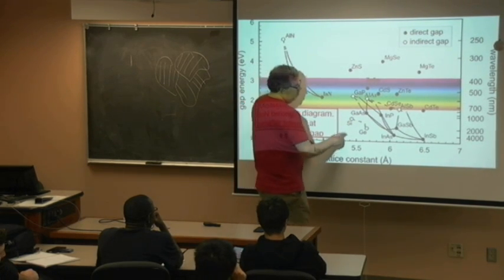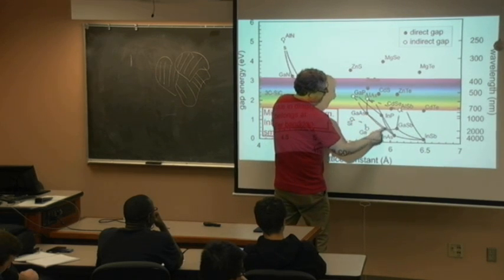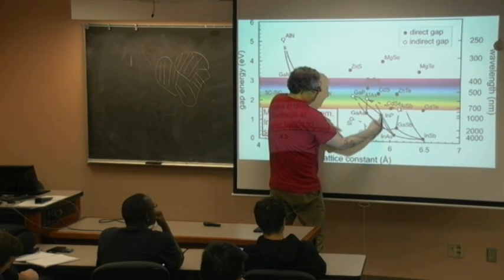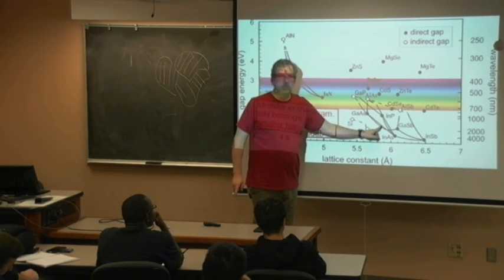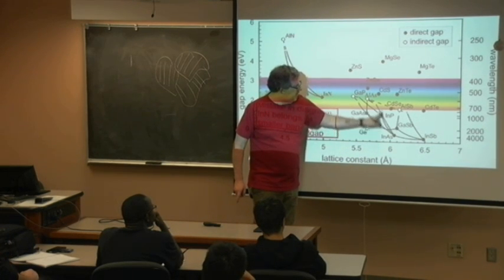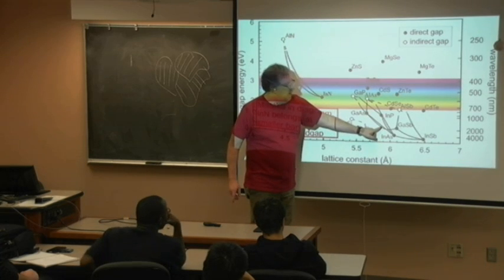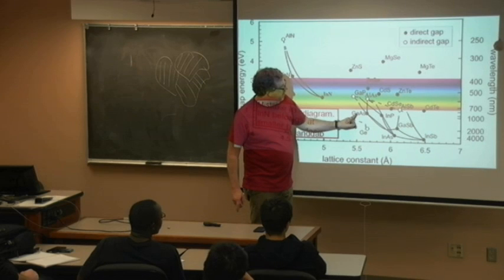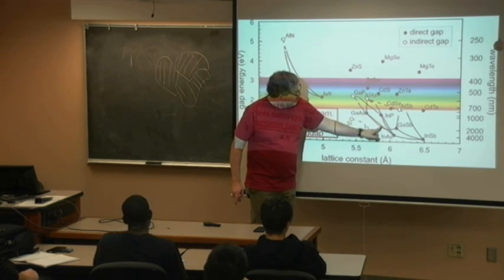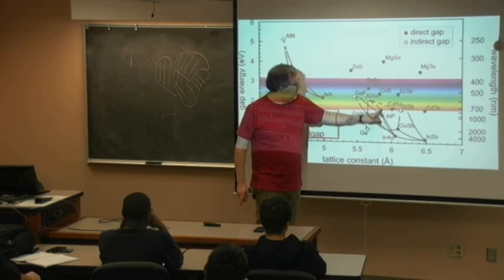But if I want to put indium gallium arsenide on indium phosphide, I probably should be right around here, and that's one of the things I used to do in my PhD. You put indium at 53% and gallium at 47% with arsenic right there, and you'll be lattice matched on the indium phosphide. So you're right there.